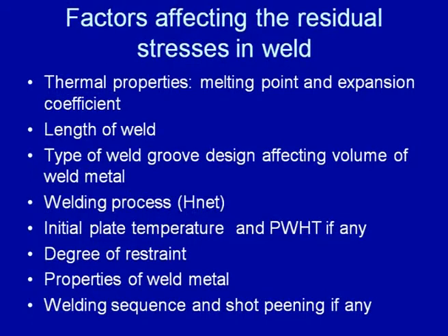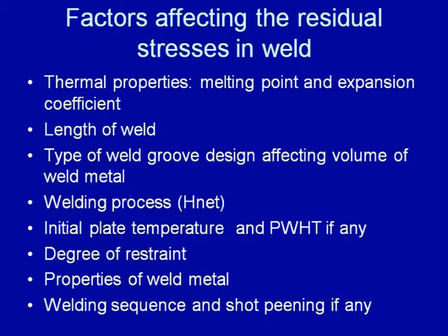So, one is the thermal properties that will affect the residual stress magnitude, because the greater the melting point and the higher the expansion coefficient, the greater will be the possibility of higher locked-in strain, which in turn will result in higher residual stresses. Similarly, with the length of the weld, in general an increase in length increases the residual stress up to about 300 mm, and thereafter no major increase in the residual stress magnitude is observed. This is what we will be seeing in the subsequent slide.